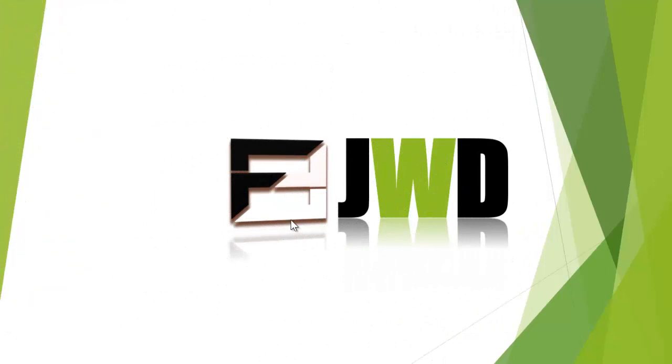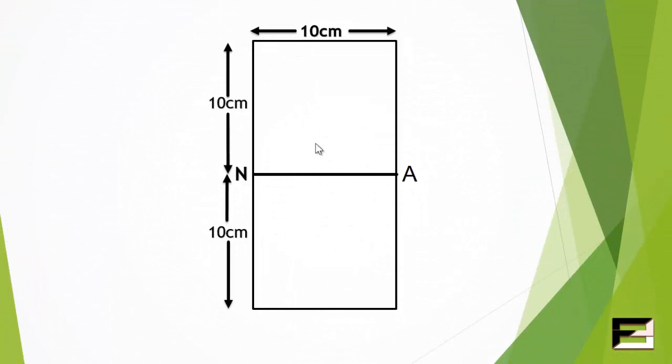Today we are talking about maximum bending stress in a beam. We have a beam 20 cm in depth and 10 cm wide. We have to determine the radius of curvature and also the maximum bending stress. This is the depth of the beam, 20 cm.